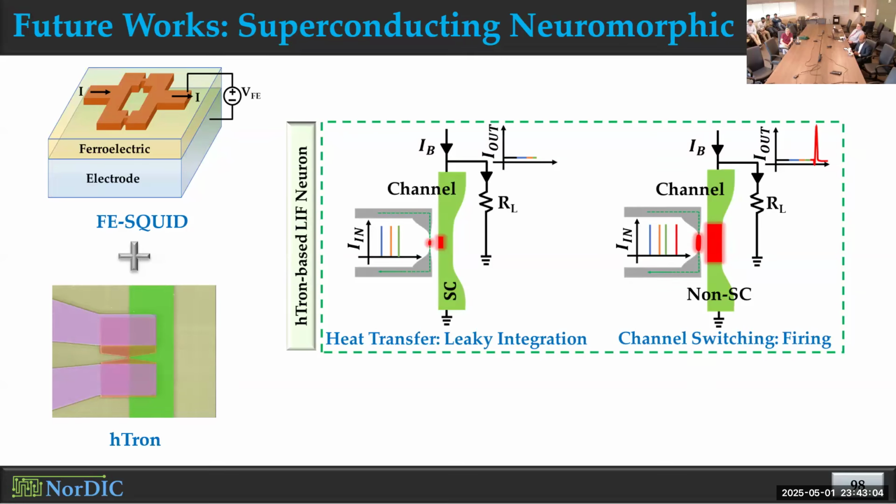And we designed that in a way so that we get that separate read-write path capability. That's what enables the advantages that I talked about compared to memristor. That's why we're comparing these two memory-based devices with memristor. Memristor is just an example. You can replace memristor with other memory technology as well. If you take ferroelectric memories or spintronic memories instead of memristor, the same thing will apply, so we'll have the same advantage there. We are more familiar with memristor because we have worked on that as well. That's why we use memristor to compare, but you can use other memory technologies as well.